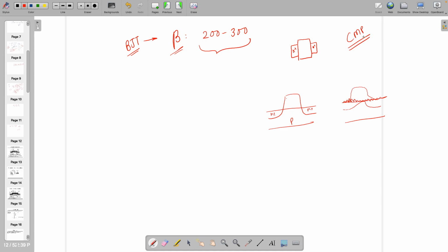If you look at the chip, on top of that chip, these are different layers. So at the end, it looks like this one. So it has to be polished and made flat. Then doing all this will not give you a guarantee that one chip looks like this one, while another chip might be something like this also. Anything can happen. You might have some variation. So it is very difficult to make such a chip exactly identical, and going to a low technology node such as 3 nanometer, it's becoming more and more difficult, right? So here the point is, this is all happening because of fabrication non-uniformity.